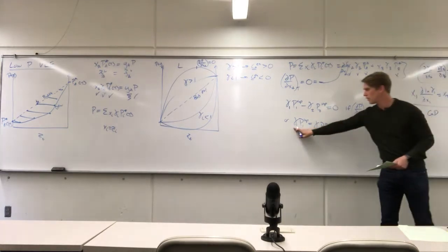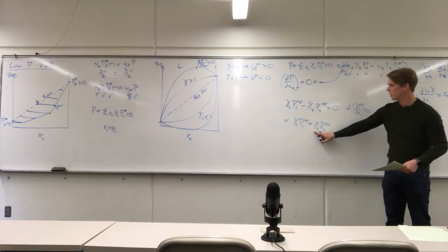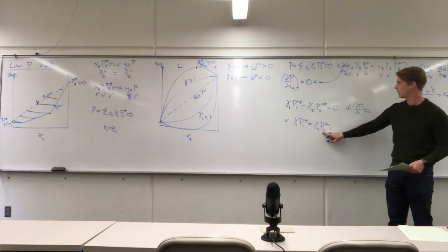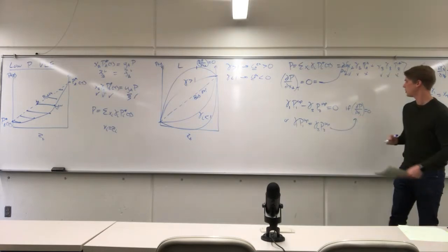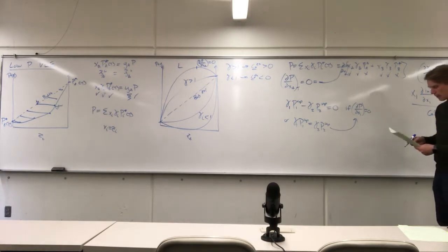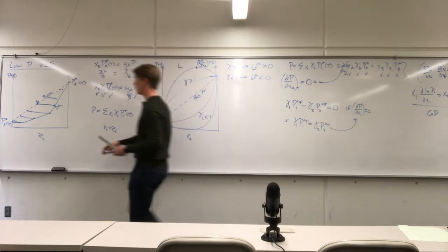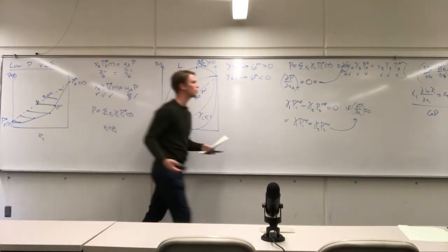The activity coefficient of species 1 times its vapor pressure is the same as the activity coefficient of species 2 times its vapor pressure at the position where you have a maximum or a minimum in either the pxy, the dew curve, or the bubble curve. So, why does this matter? Let's evaluate the consequences of it and demonstrate how this gives us an azeotrope.